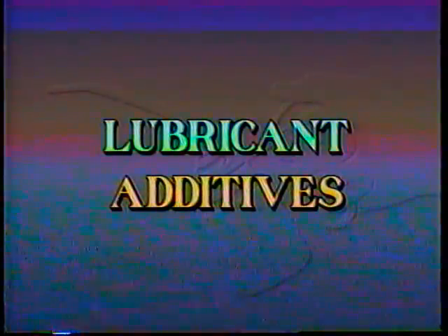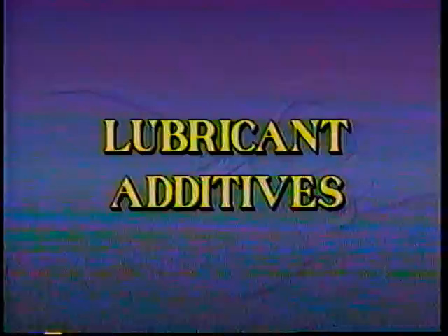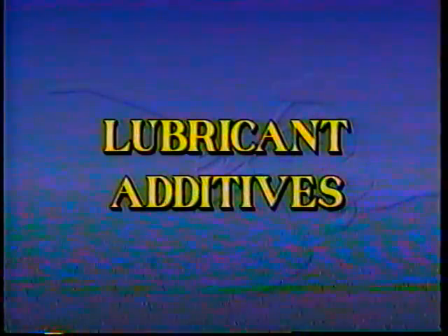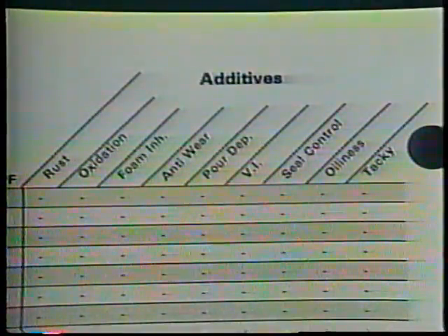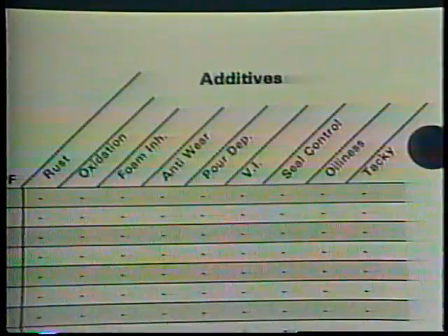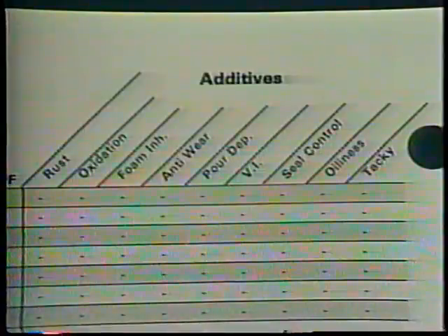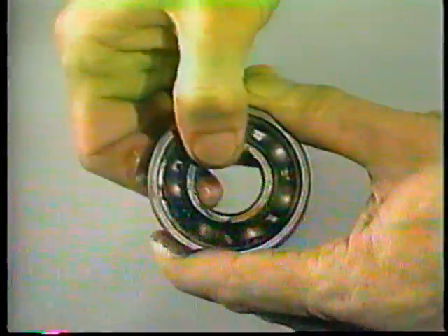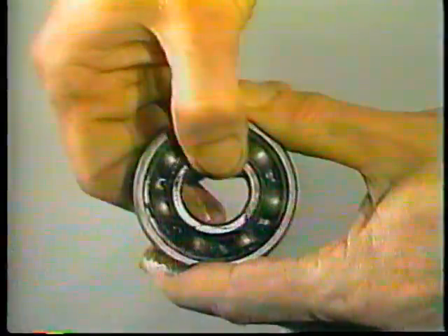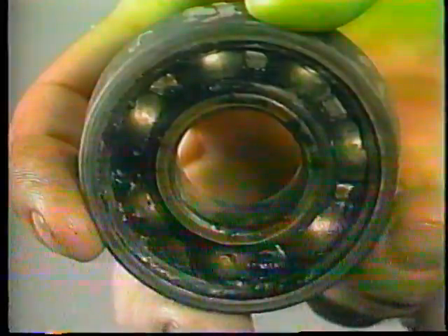To improve the properties of the oil and grease for particular applications, lubricant manufacturers often include additives. In applications where gears or other moving parts may whip air bubbles into oil, anti-foaming additives help release the bubbles quickly. Many oils and greases include special additives to prevent oxygen from combining with metal parts to form rust, and to prevent oxygen from combining with the oil. However, even with these additives, oil or grease will oxidize if it is kept hot enough for long enough. When that happens, the oxidized oil or grease will lubricate poorly, and they may corrode some kinds of metals.